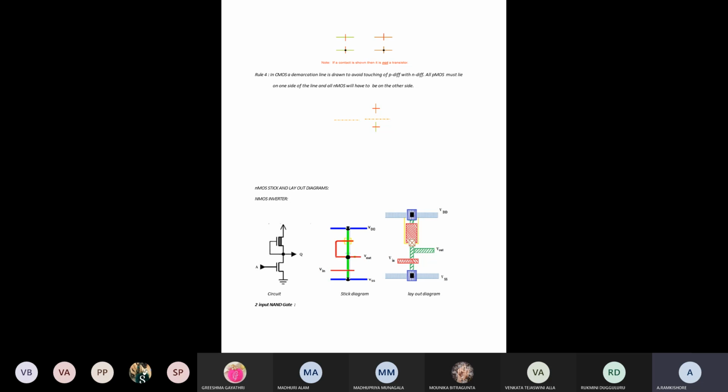Up to one part for the NMOS depletion mode transistor we take green color. Below it we also have the NMOS transistor, so the same green color will be extended up to the ground level. We fulfilled the NMOS transistors with N diffusion.